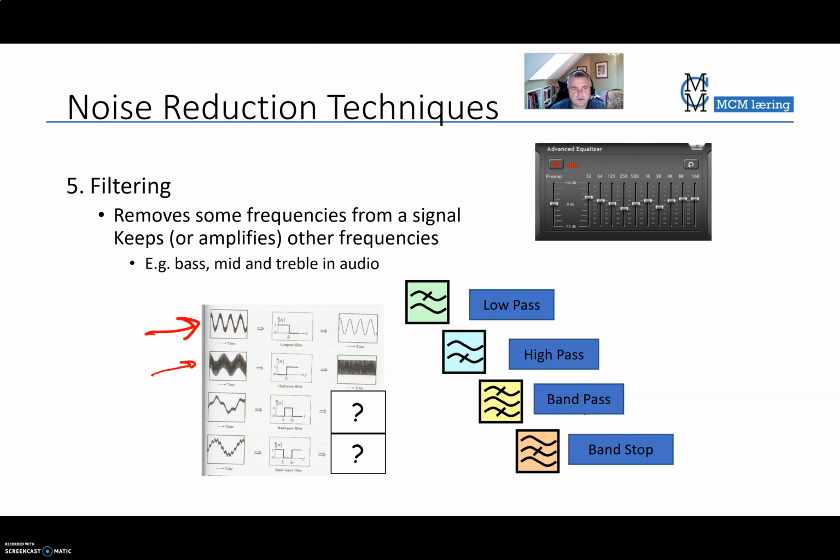Well, that's how it looks, just keeping the high frequency component. A band pass will actually remove high frequency and low frequency and keep the frequency in the middle. If you see here, we have a very high frequency that makes more or less a gray band on top of the wave. I have a very low frequency with one wave only, more or less.